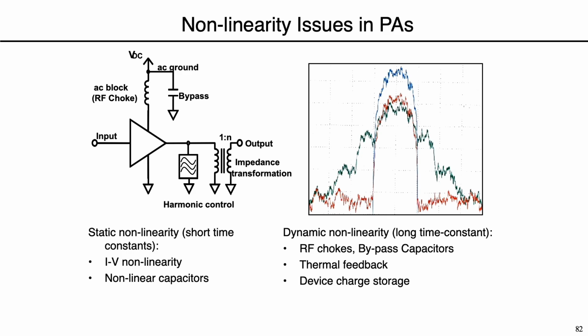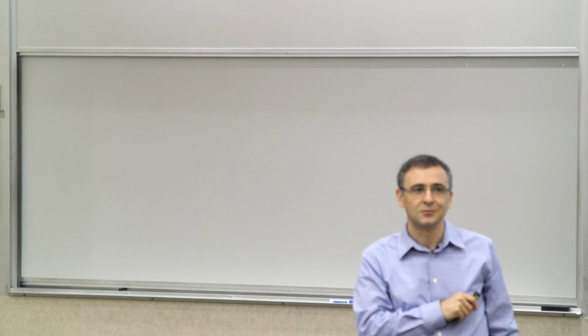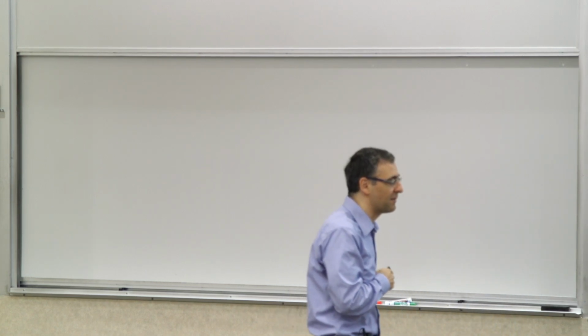So you can see that these parts that were clean, when they go through that nonlinearity, it's basically, you can think about it as an intermodulation between components within the spectrum that you're transmitting. Different components are interacting with each other, and the intermods would appear outside the band. And these are in some other people's bands. So other people don't like it. So you need to get rid of them or minimize them.